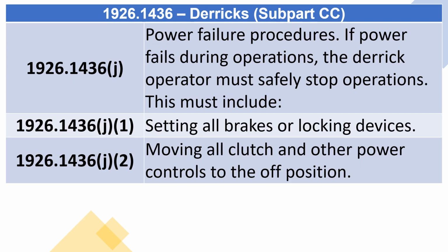1926.1436(j) Power failure procedures. If power fails during operations, the derrick operator must safely stop operations. This must include 1926.1436(j)(1) and (j)(2): Setting all brakes or locking devices. Moving all clutch and other power controls to the off position.